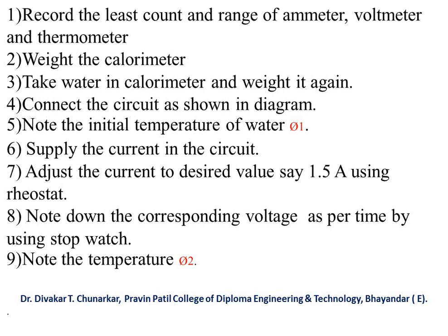So student, the function or use of the rheostat is to increase or decrease the current. Note down the corresponding voltage as per time by using a stopwatch. Note the initial temperature of water when we take it in the calorimeter, that is theta1, and after increasing, the temperature is theta2. Keep this in mind.